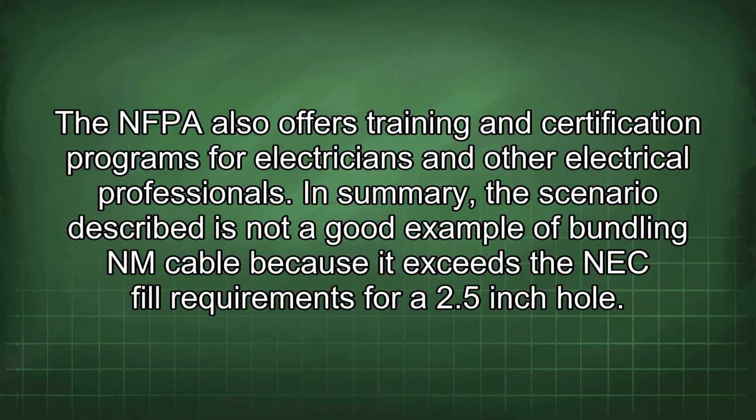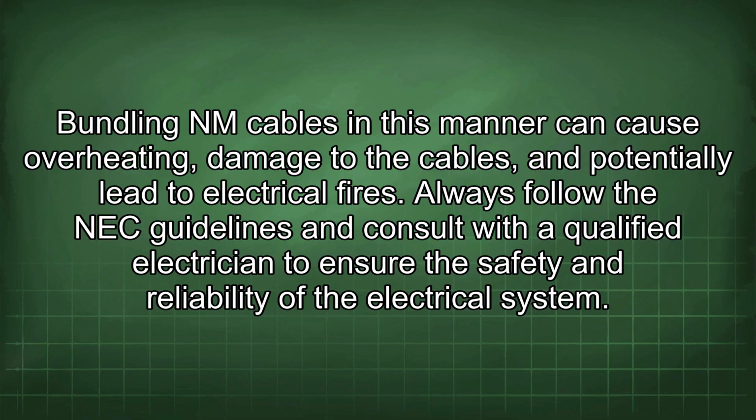In summary, the scenario described is not a good example of bundling NM cable because it exceeds the NEC fill requirements for a 2.5-inch hole. Bundling NM cables in this manner can cause overheating, damage to the cables, and potentially lead to electrical fires. Always follow the NEC guidelines and consult with a qualified electrician to ensure the safety and reliability of the electrical